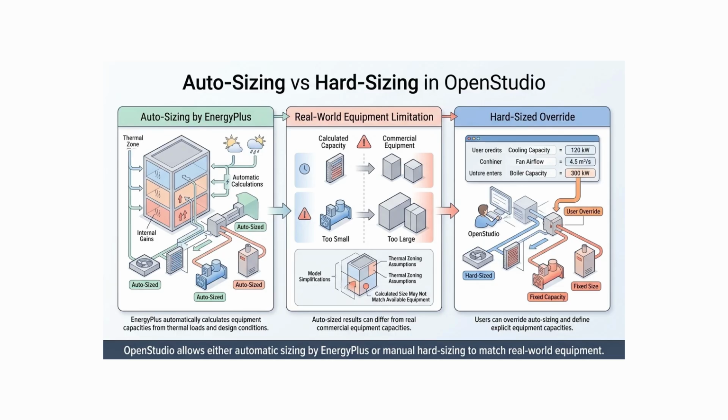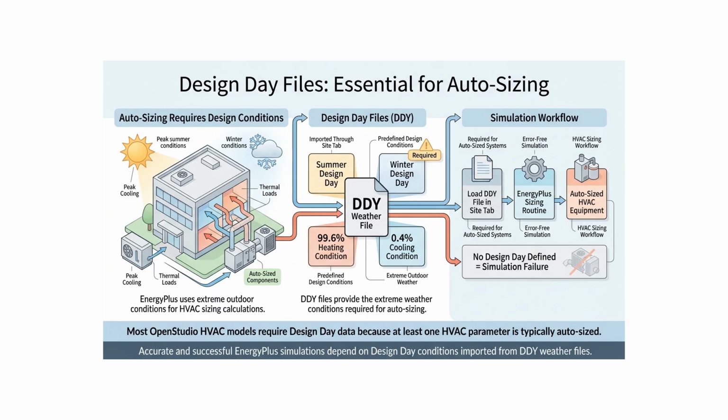simulation calculate it automatically. Now let's talk about design day files, which play a critical role in the auto-sizing process. As we discussed earlier, OpenStudio relies on DDY weather files to represent the extreme outdoor conditions used for sizing HVAC equipment. If your model includes any auto-sized HVAC components, you must have at least one design day defined, otherwise the simulation will fail to run. In practice, almost every OpenStudio model that includes HVAC ends up with at least one auto-sized parameter. So, including design day data is essentially required for accurate and error-free simulation.